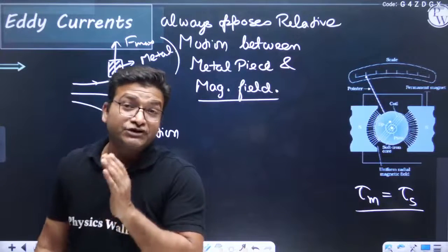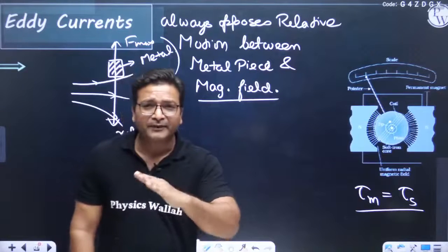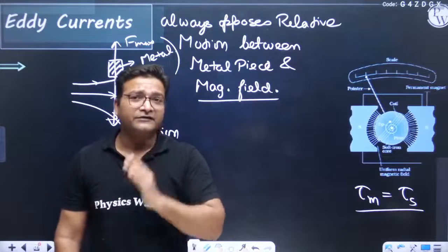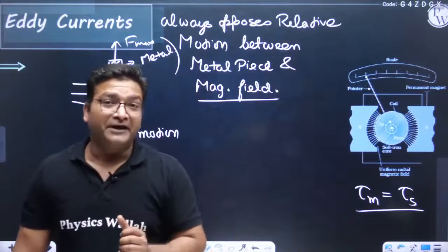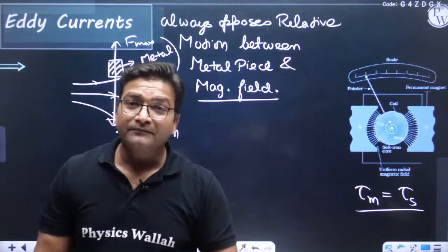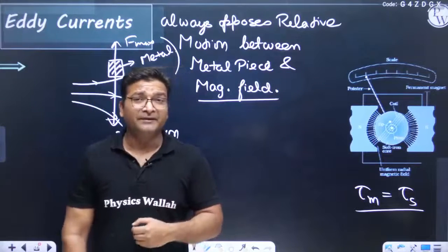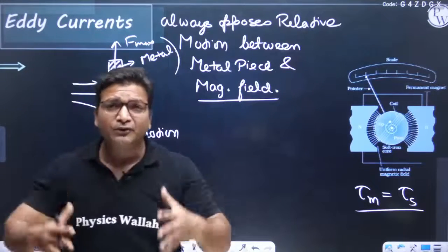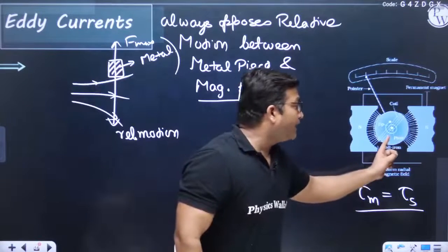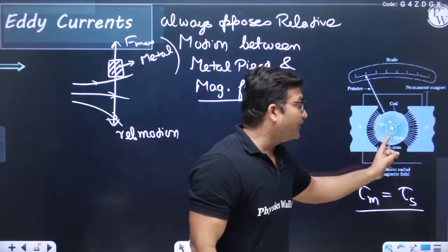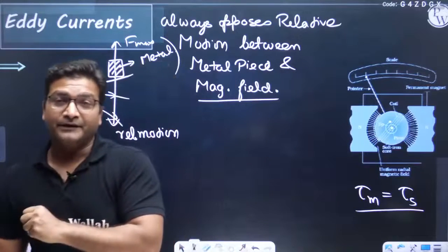But at the position of equilibrium, the pointer vibrates a little and then it halts, then it stays. So to avoid these vibrations, we need some damping. We could have used air friction damping or oil friction damping, but we do not use any additional damping here because this soft iron core acts as a very good electromagnetic damping.